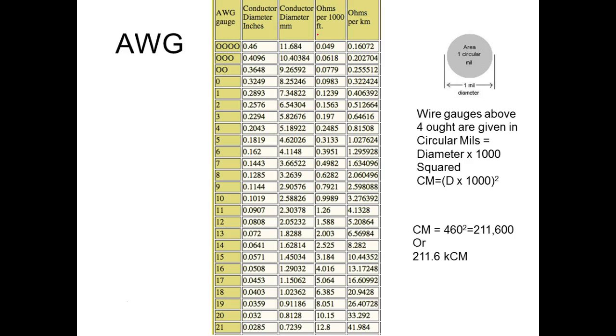So notice the resistance is rated in what? Ohms per 1,000 feet. Now as the gauge number goes up, the size goes down. So 20 gauge wire, we use a lot of 22 gauge wires in here, so it's going to have over 30 ohms per 1,000 feet, but we're only using wires that are what, 6 inches long. So how much would it have for 1 inch, right? It'd be down in the milliohms, which we can ignore, right? In fact, most ohm meters won't even measure it.